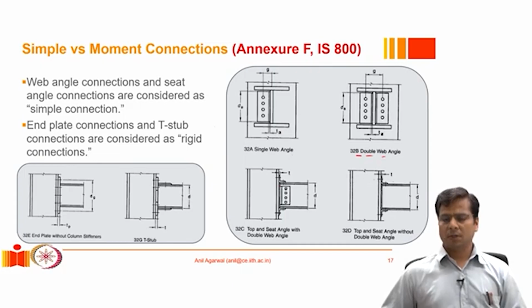Right. So actually there is no contradiction. These connectors that we are providing have very high stiffness against shear. So for example, this seat does not deform much before it starts resisting shear. However, when this system is subjected to moment, that is a rotation demand in the beam, you would observe that this angle can deform quite a bit in this direction. When it is pulled inside, it can resist the load very effectively, but when it is pulled outward, it cannot resist much load and it will deform very easily. Therefore, these connections are relatively very flexible when they are subjected to moment demand,